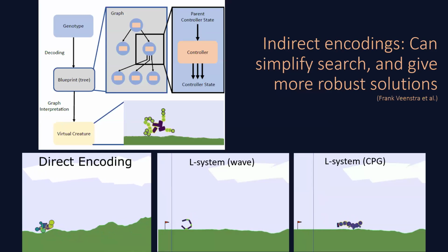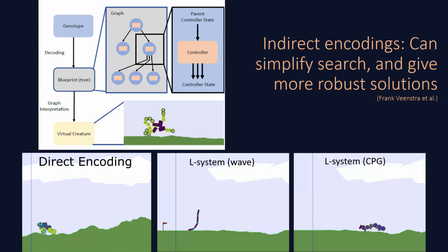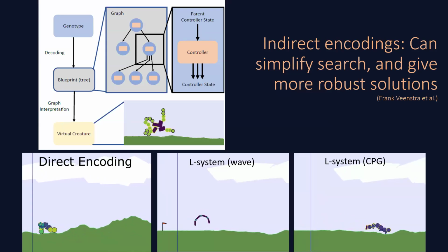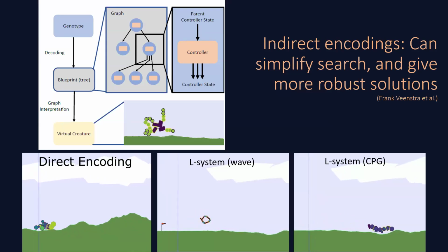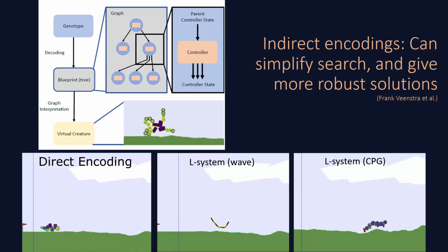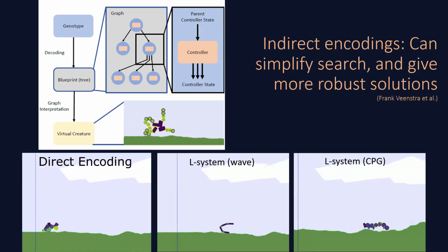Yeah, that's a good question. How to initialize the genome. Probably the most common is just to randomly initialize it, within some ranges that you know make sense, so that you start with very bad robots in the beginning, and then they will get better and better over time. If you have some ideas about a good one, you can insert them into the population. It's called seeding the evolutionary algorithm. So you can start with something that makes a bit more sense.